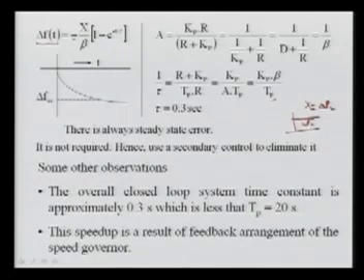So you can see the frequency response will follow this curve, shown here. The time constant of this whole response is now about 3 seconds, when Tp was 20 seconds for the example I considered in lecture 2. For that case, if you consider R, Kp, D and Tp, we get tau approximately 3 seconds. We can observe from here that there is always a steady state error.